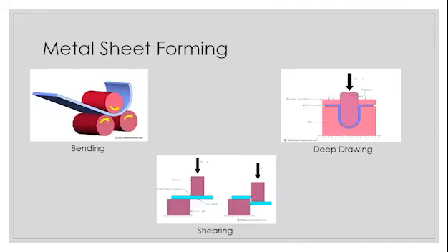The next process is squeezing. Squeezing is one of the most useful forming processes. In this process, a die is used. The die should be a closed type die. At first, the die is heated, then molten metal is placed in one part of the die.